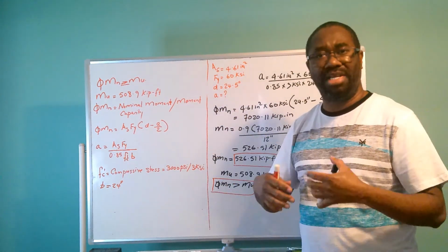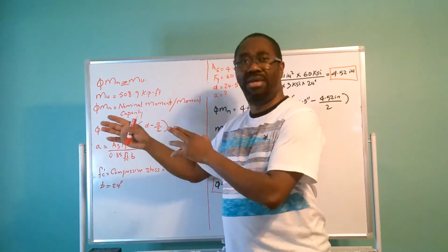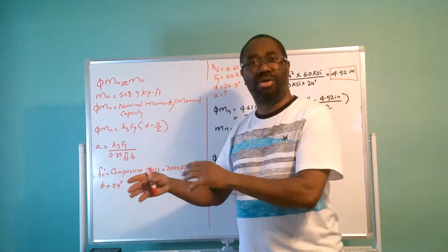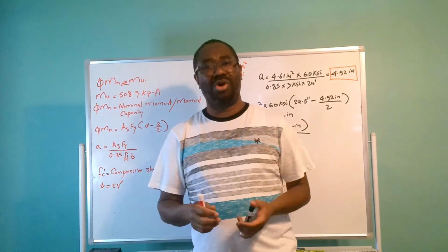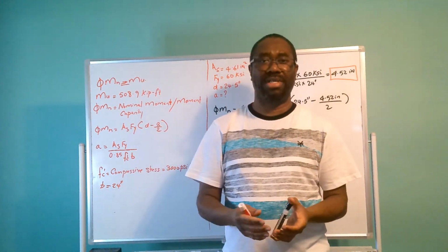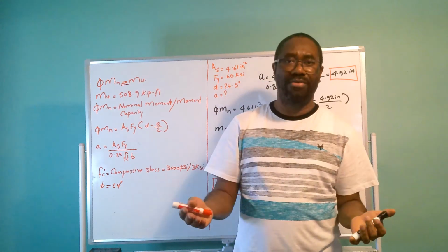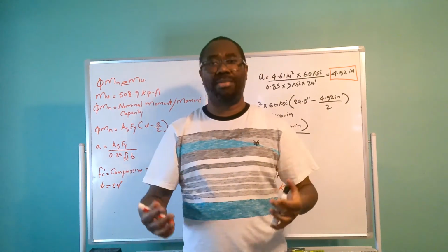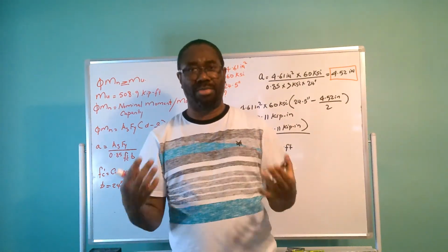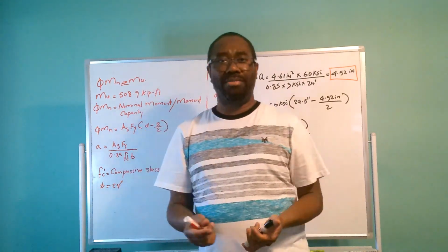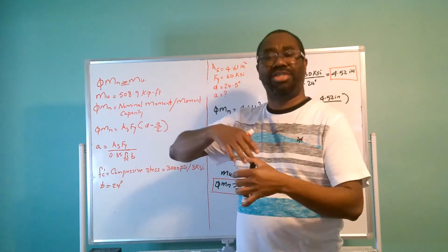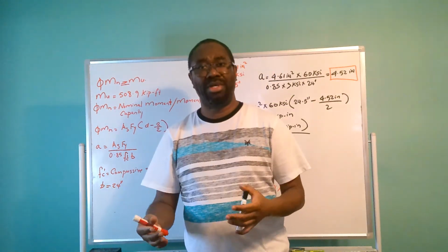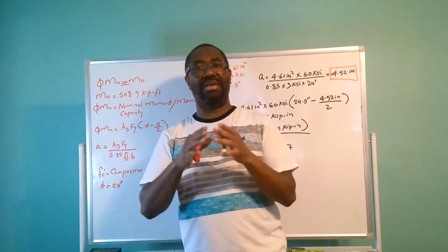The 6 1-inch bars can resist the load due to bending, so our beam is okay. Now we have to do our shear reinforcement, which is really about the spacing of our stirrups. So join me in the next video when I calculate the shear reinforcement for this beam to complete the design of this beam.